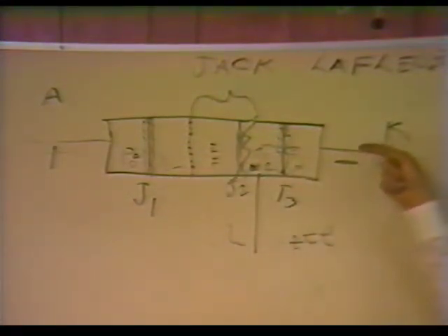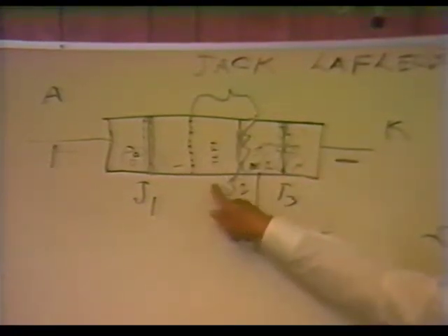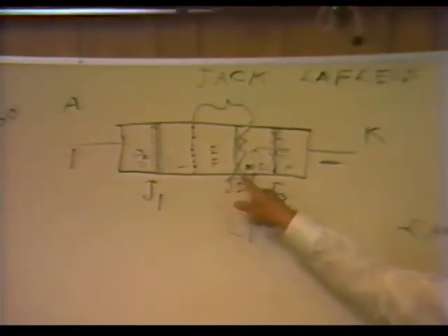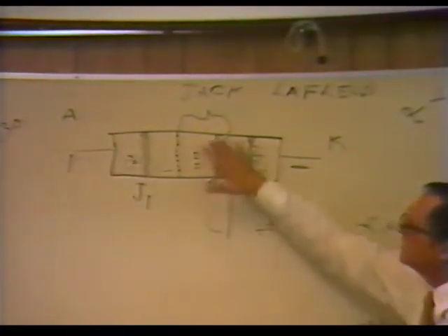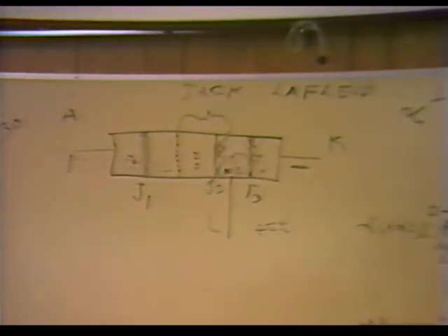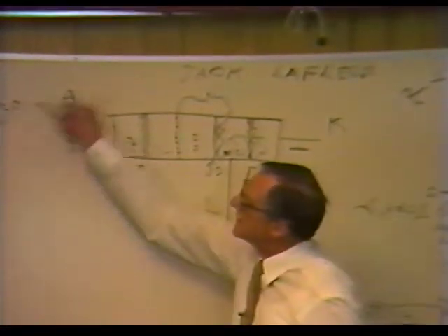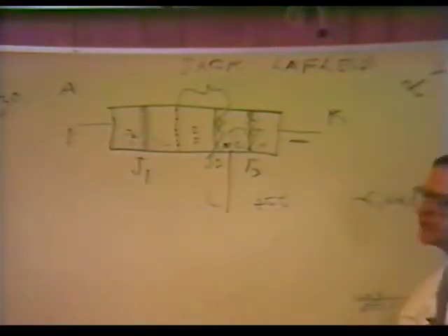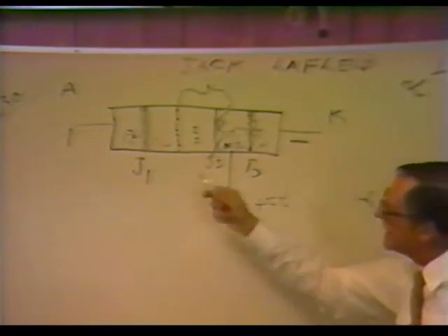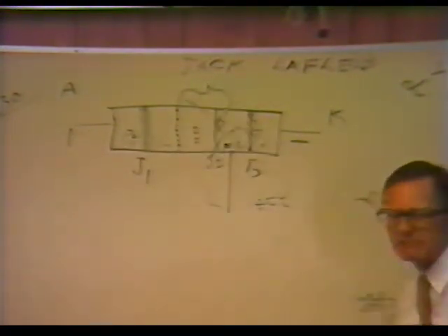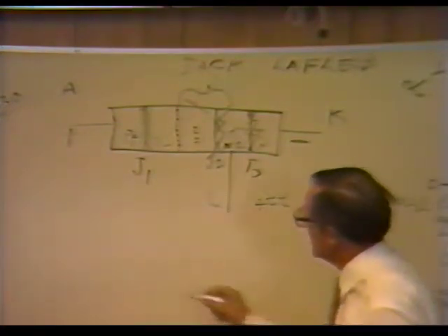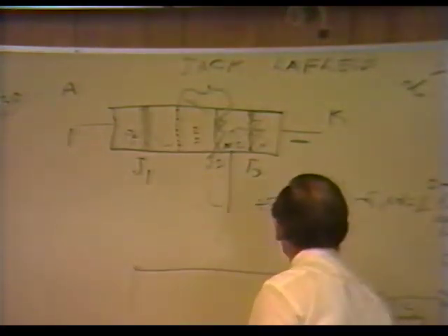So we have electrons flowing through the region and are collected here. We have holes that have gone through the region and are collected here. This junction cannot sustain the 30 volt hold off that it tried to do. The junction breaks down and we go into conduction. Now the SCR is a very low conduction path because this field has collapsed. Now what does it look like when it goes into conduction?